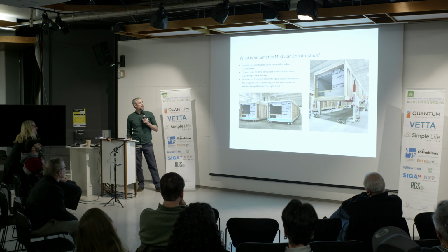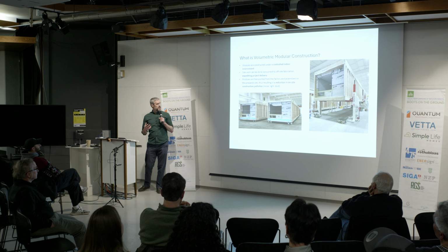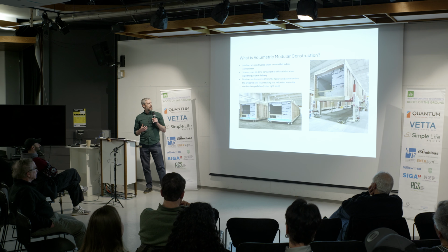Okay, so I'll start off. What is volumetric modular construction? If anybody has ever bought an IKEA cabinet and installed it in their house, that is modular in nature. That is modular construction. That's flat pack modular. Full volumetric modular construction is where the entire 3D space from start to finish is constructed off-site and delivered to site.